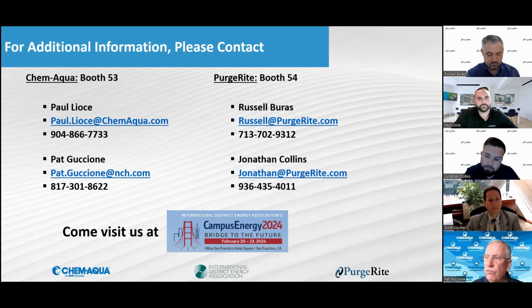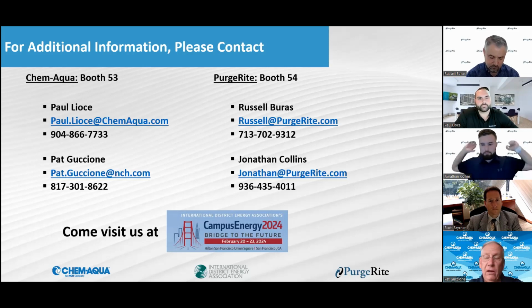The other thing to consider is it may be worth the small amount of extra money to buy an already inhibited glycol that comes with a corrosion inhibitor built in. That way there's no compatibility issues. And it's all in the same house. And I will say that our experience with the inhibited glycols is generally very positive.